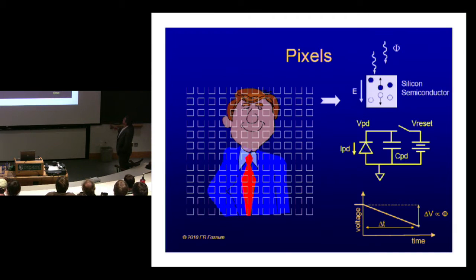So we've basically gone from light to electrons, and electrons to voltage, and from that voltage we can kind of infer how much light was falling on the device. So all we need to do is just read out this voltage and go into an analog to digital converter, and we've got back kind of a map for each one of these pixels of what the light intensity was.